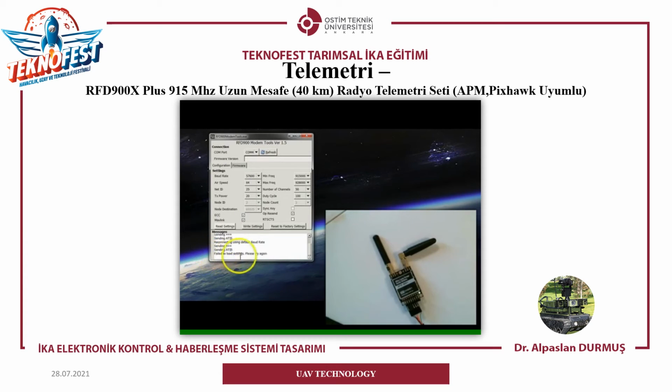Now anytime you get this error, 99.9% of the time it's because you have a baud rate mismatch. When your radio is at its very initial factory setting, it is set at 57,600. So if you've never configured a radio before, you will leave this setting at 57,600 and read the settings. If you've changed the baud rate at any time, you'll have to match the baud rate with what it was set at.